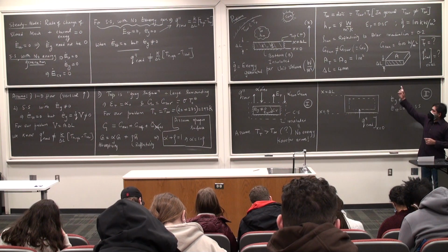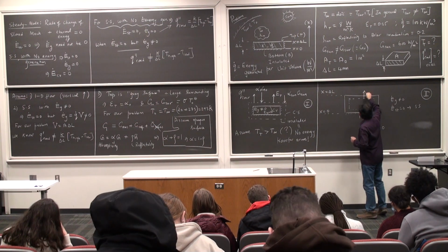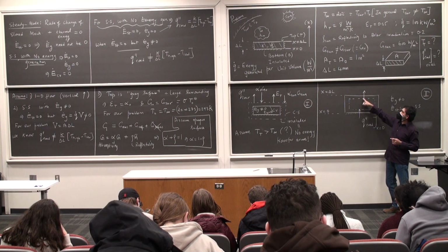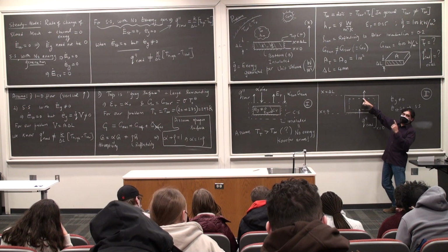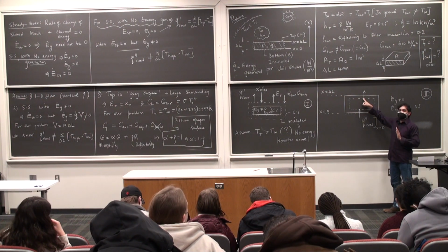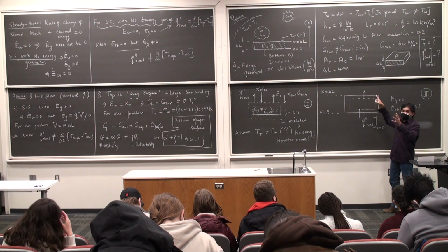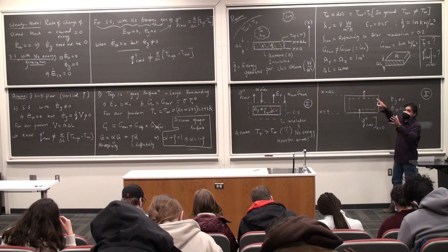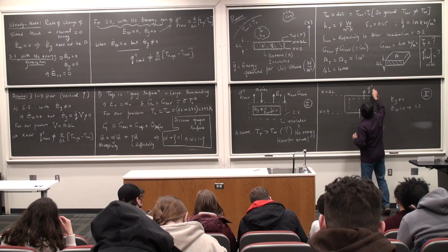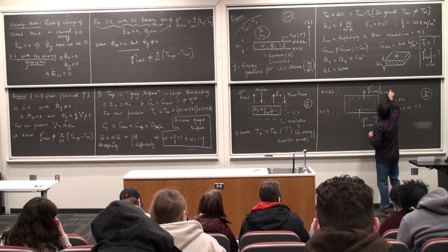Then I'm going to have something going out. Obviously, if heat comes in, it has to go out. So I'm just going to draw it this way. The significance of this is just energy transfer taking place across this control surface. It's not penetrating and going out through the body. It is taking place within the body, within the medium. There is no bulk motion within the medium, so the only form of energy transfer due to heat transfer is conduction, which is why we call it conduction. This is Q conduction at x is equal to delta L.